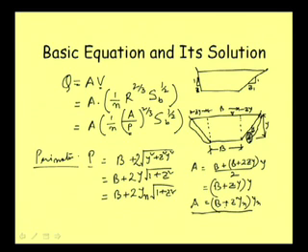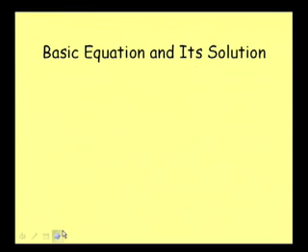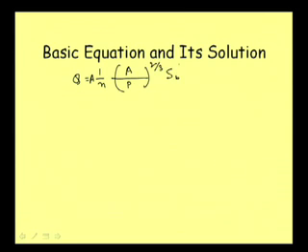Now, substituting these values in this equation, let us see what form of equation we are getting. Well, Q is equal to 1 by n, then A to the power 2 by 3 was there, and then there was another A here. So we can write, let me write it here itself, A here and A by P to the power 2 by 3. Let me keep it in this form, and S b to the power half.